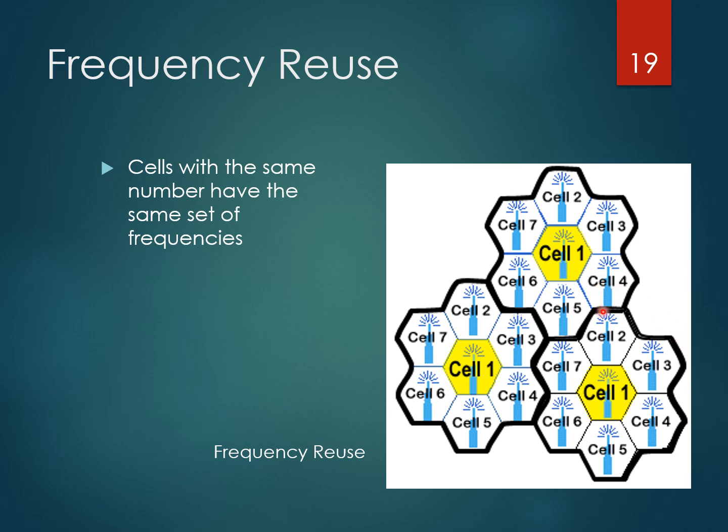This is the first cluster, this is the second cluster and the third cluster. For example, cell 1 frequency, if you are allotting 850 megahertz to 950 megahertz in the cellular region, we cannot utilize the same frequency in the nearby cells, but we can use the same frequency in the nearby cluster. The 850 to 950 megahertz frequency can be utilized in this cell, not here.